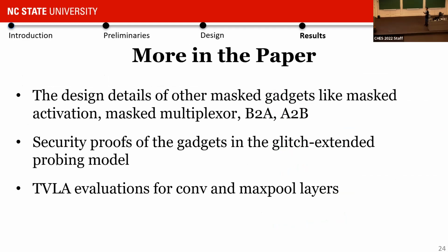In addition to what I already presented, we have more details in the paper on the masking gadgets, how we actually implement them, and the security proofs of those gadgets in the glitch extended probing model. We also did TVLA evaluations for the convolution and max pool layers.